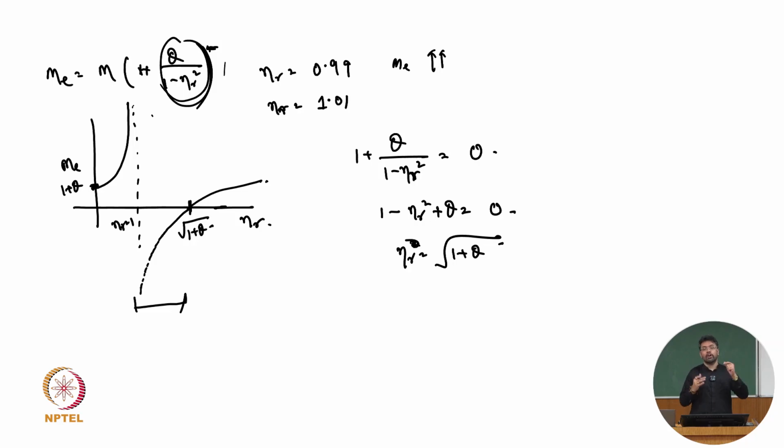Why? Because of the internal resonator, which is in out of phase vibration, and the internal resonator is taking more and more excitation compared to the external one. Therefore, as the resonator is oscillating more in the out of phase direction, the overall momentum change of the system seems negative.